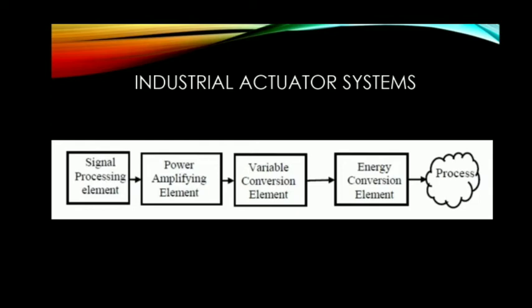Industrial actuator systems. Actuation systems convert the input signals computed by the control systems into forms that can be applied to the actual process and would produce the desired variations in the process physical variables. In the same way as in sensors but in a reverse sense, these systems convert the controller output, which is essentially information without the power, and in the form of electrical voltages, or at times pneumatic pressure, in two ways.